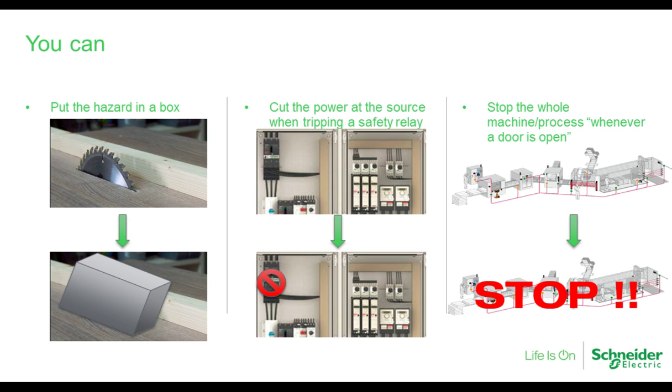But whatever it is, the first thing that we usually think of is taking that hazard and making it impossible or very, very difficult for somebody to come into contact with it. So sometimes we loosely call it putting it in a box or guarding it, blocking access.